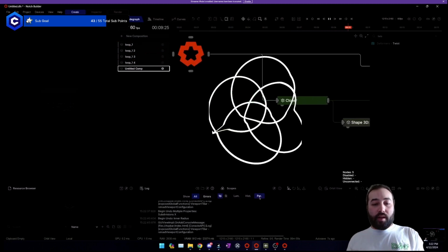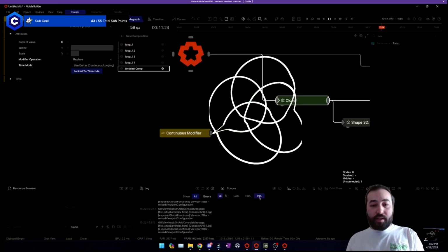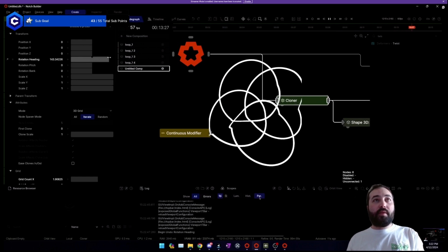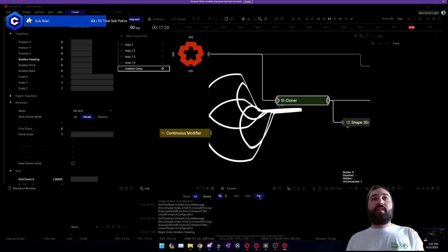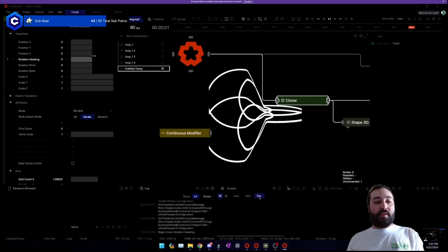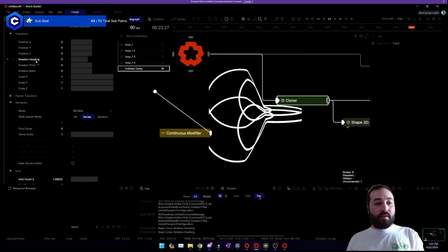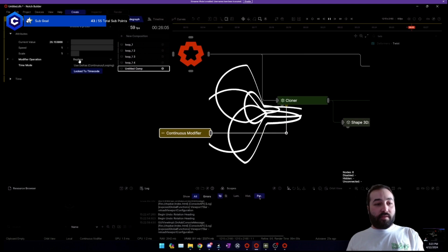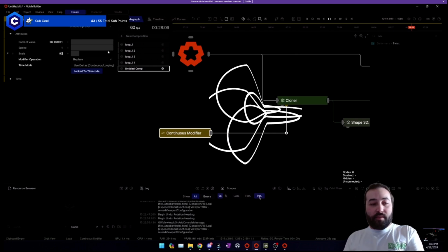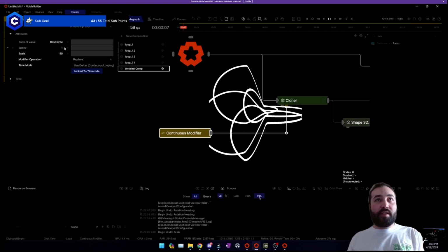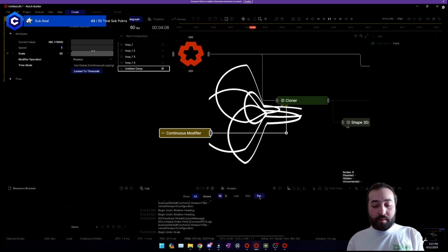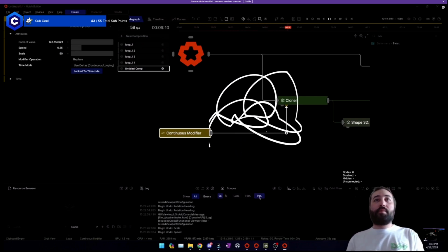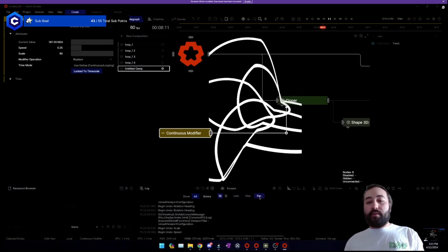Cool. And now I'm going to add my continuous back so we could make it into a loop. And you see when we're looping it, it's moving through the deformation, which is pretty cool. Oh, that's cool. So we're just gonna make the scale 90 because it's 90 degrees to get to the loop since it's 4 of them. And we're gonna make the speed 1/4, so it's a 4-second loop. And now we have this.